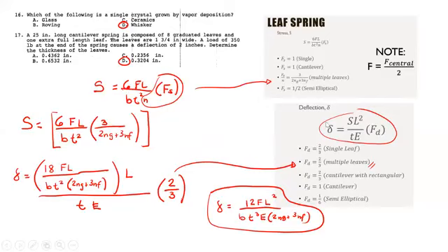So, next, problem number 18, determine the torque that can be applied to a 1-inch diameter circular shaft if the shearing stress is not to exceed 8,000 PSI. So, medyo madali lang itong 18, no? Dahil stress is equals to 16T over pi d cube lang. So, formula ng stress ng shaft lang.